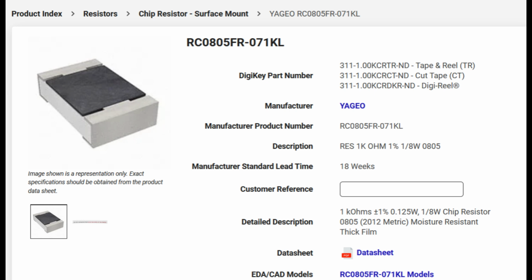For many commonly used parts, Altium Designer already provides default schematic symbols and PCB footprints. These built-in libraries are sufficient for standard components such as resistors, capacitors, inductors, and diodes. Using default libraries simplifies the design process and significantly reduces development time. While placing components, it is important to verify that the selected footprint matches the actual package specified in the datasheet. If a suitable model is available in the default libraries, it can be directly used without creating a new component.